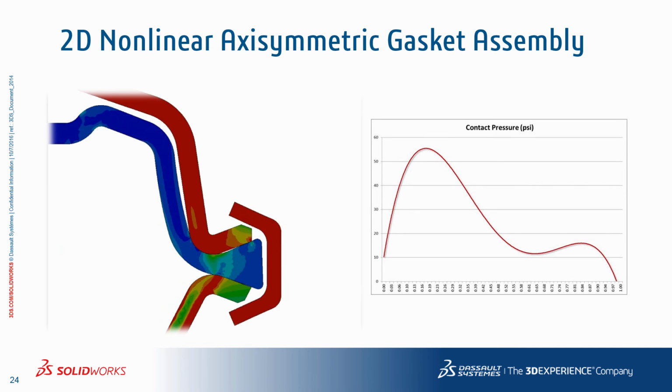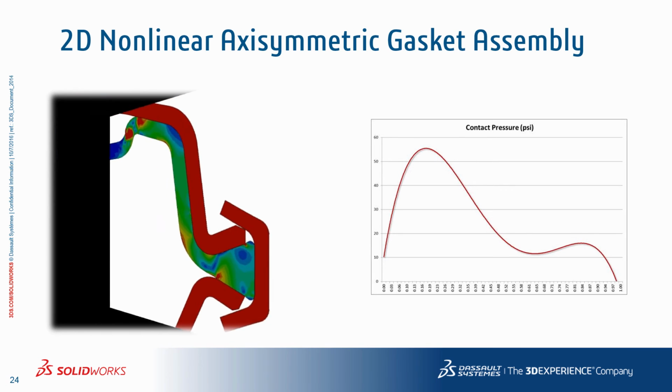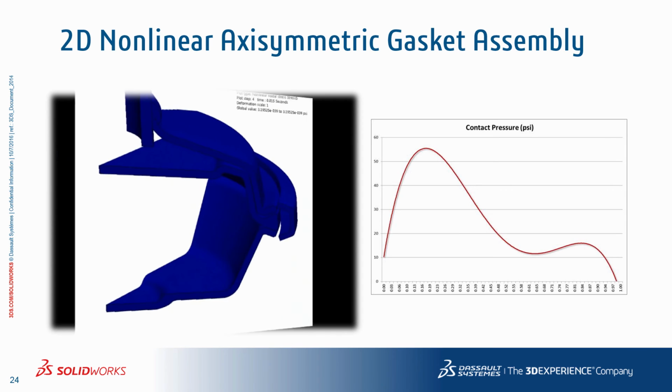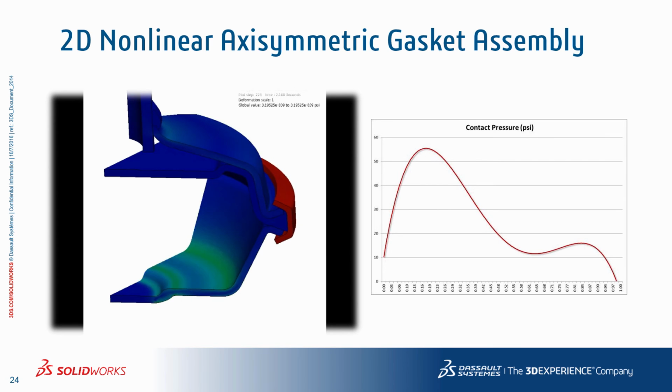Notice in the video how the top and bottom plates squeeze the sandwiched elastomer first and then a side clamp is pushed, creating further deformation. You can clearly see how the contact pressure or the stress and the contact areas are constantly changing as the squeeze force increases. This cannot be captured by a linear system or by making any assumptions on loads and fixtures. Bottom line is contact nonlinearity is the right way to solve these types of problems.